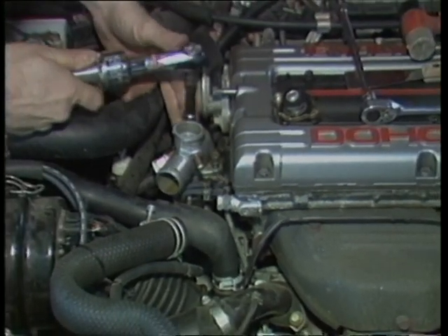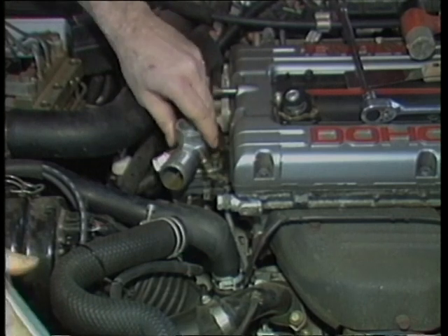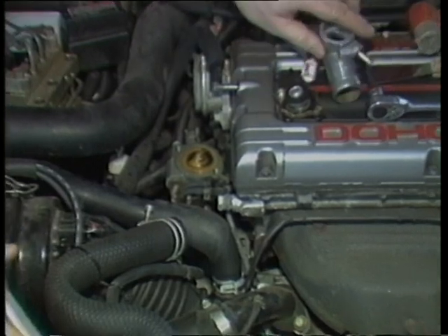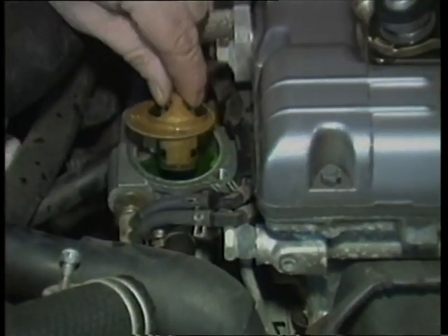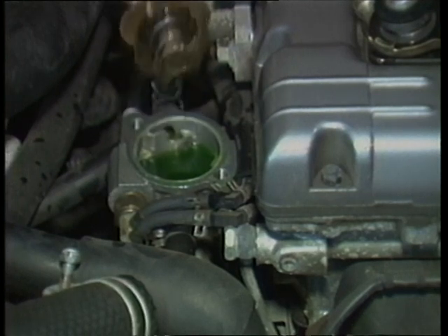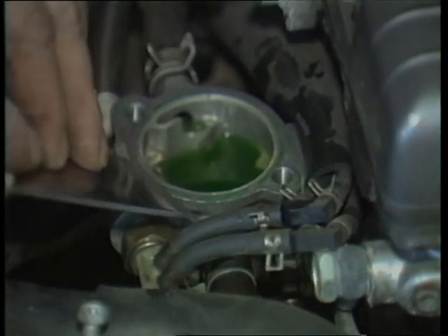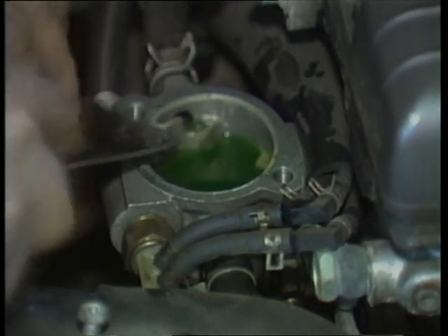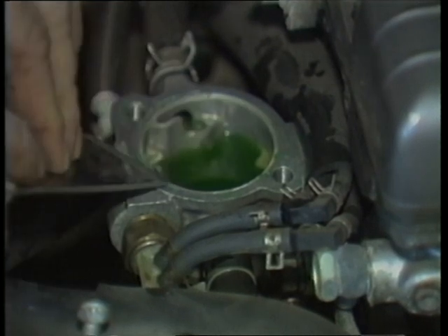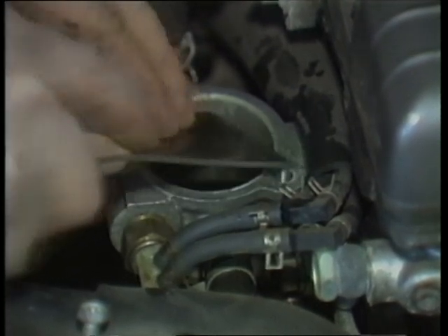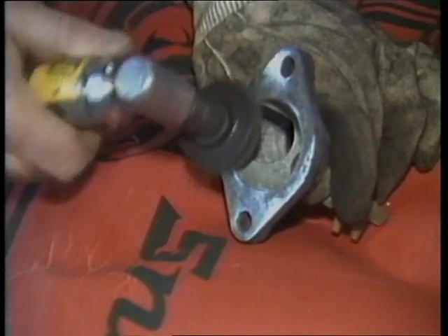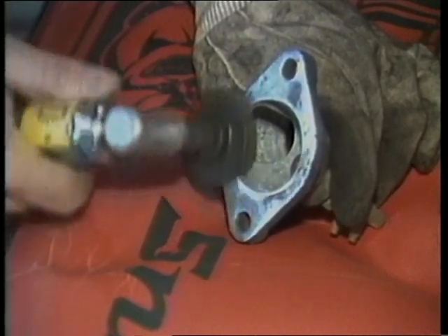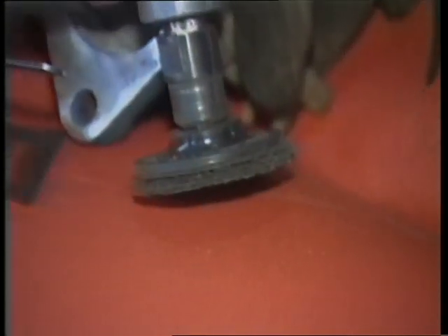Instead of hot plate testing of the thermostat, most mechanics simply install a new thermostat when the old one is in doubt. Clean off all old gasket material from the sealing surfaces on the engine and on the housing. You can use a gasket scraper or a special scuff pad mounted on an air tool. When scraping, do not gouge or nick gasket surfaces. The air tool is obviously much faster and will save time compared to a gasket scraper. The scuff pad will remove old gasket material, but it will not remove and damage the metal.